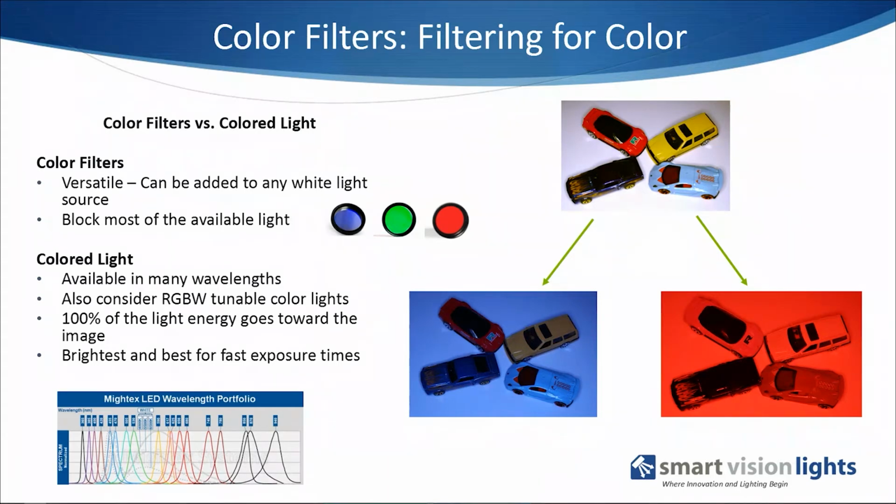And often these inspections are dynamic, there's motion, and you want a fast shutter time. So color filters can be versatile and cheap, but they also block most of the available light by the definition of a color filter.